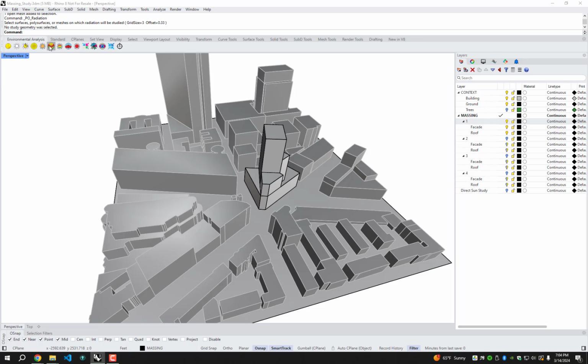Because these radiation benefit studies are something I know a lot of people really love to run, especially in early design. The basic idea is that I just clicked on this PO Sky Dome benefit here. We're doing a radiation study, but we're using the temperatures in the EPW file and their relationship to a balanced or neutral temperature to say, is this solar energy helpful winter sun, or is this harmful summer sun that's going to raise our cooling load?